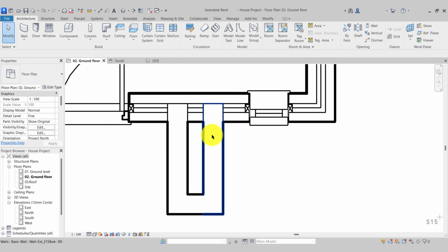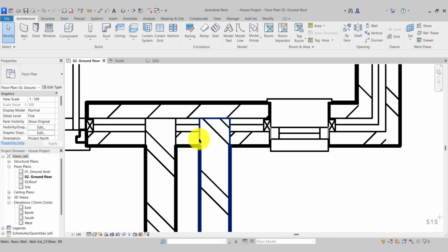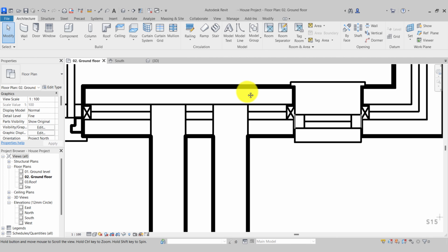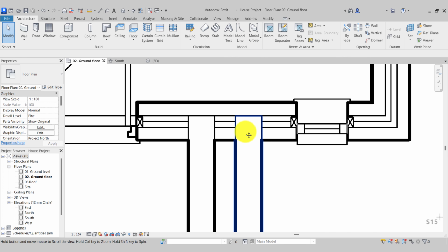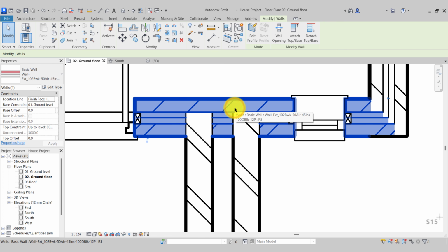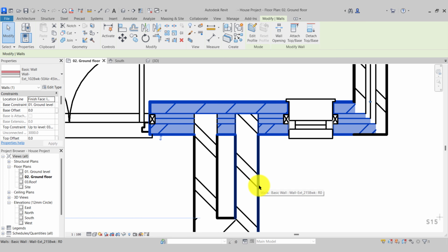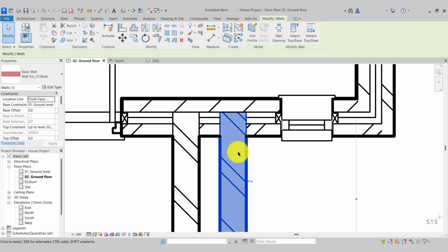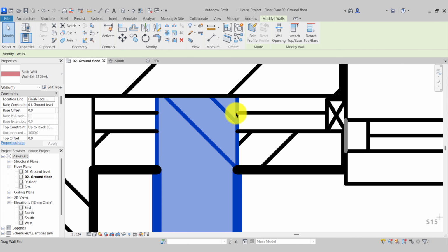So when I draw them in, you can see the brickwork is cutting right through our brick cavity and insulation to attach to the blockwork. So the core boundary of this brick is looking for the core boundary of that wall. So in reality, we don't want this to happen. So what we'll do is we'll select the brick, and at the end there's a small blue circle.